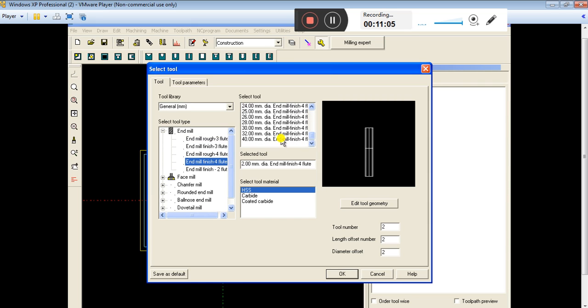Select the maximum one or 30 mm. The selection depends on the operator, which tool he has to select, depending upon the metal removal rate or the finishing he requires. Depending upon that, he will select that one.